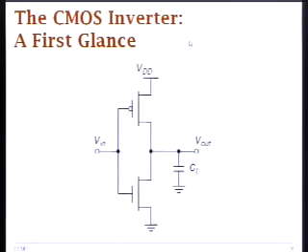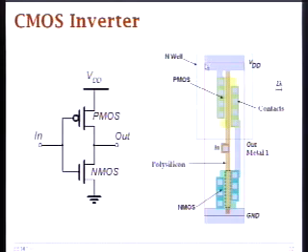on. So now let's take a look at this inverter, and this is a physical representation of an inverter. That's what you're going to be doing in labs this week. So you have common polysilicon that defines the gate electrodes, and then you have a PMOS on top and an NMOS on the bottom, and you have their drains connected to each other through this metal one.